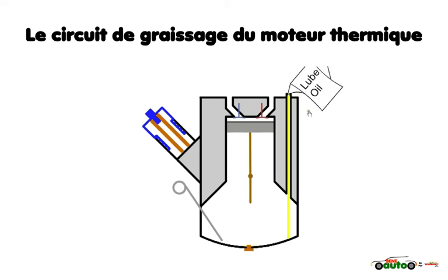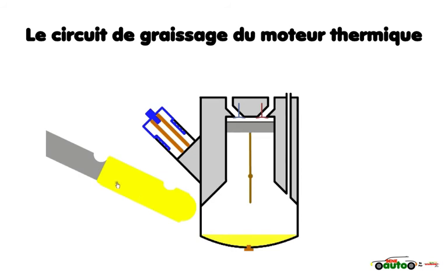The sump is now filled slowly with new oil to the desired level. When the oil is allowed to settle, the level can be checked with a dipstick. The level should be at or just under the high level mark. Fit the oil cap and clean any oil spills.